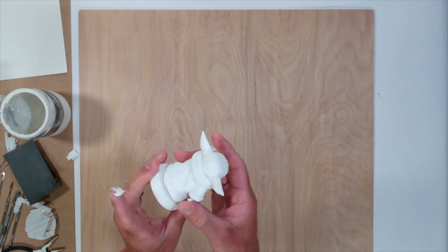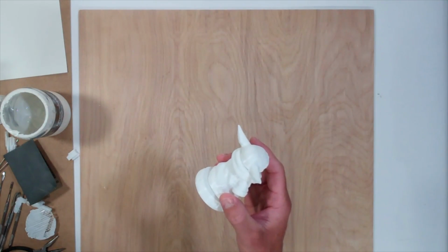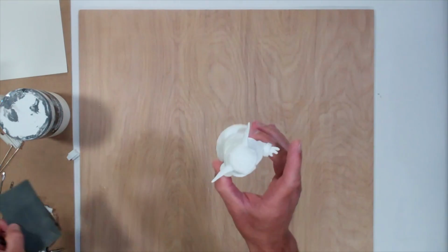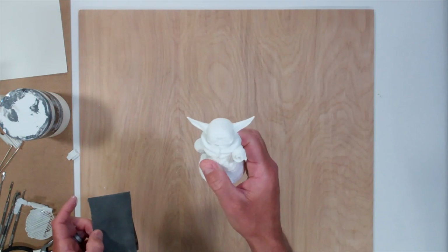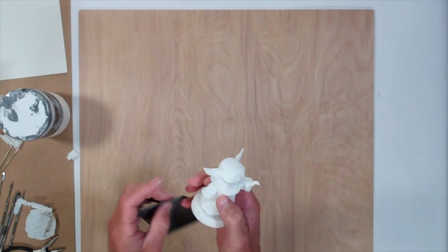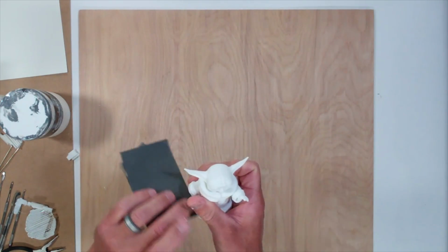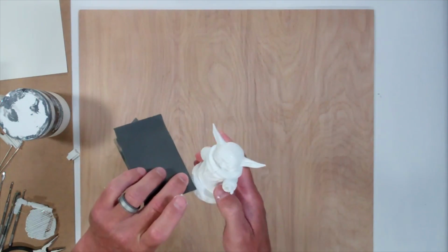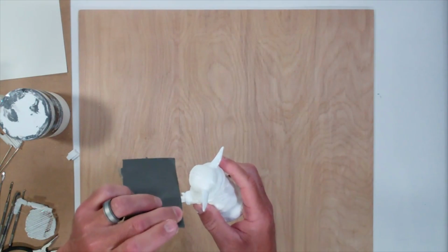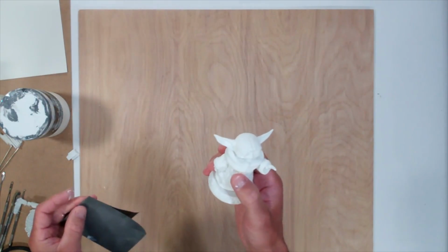So after you get everything cleaned up and fixed and put together, and you've got your raft and perhaps your supports off of it, if you need to use modeling paste, let that dry for 24 hours. Then it's time to start sanding. Very, very lightly sand the top of the surface. Take off any little extra filament. Sometimes there'll be little filament streamers that are left from the nozzle head traveling from part to part as it prints. You're going to want to get rid of all of that.